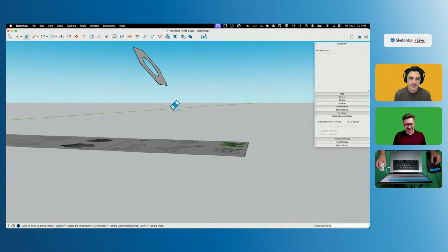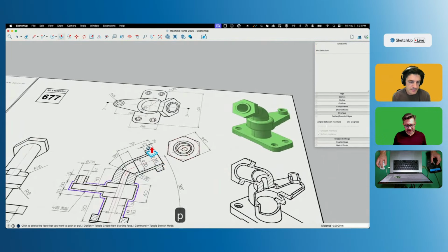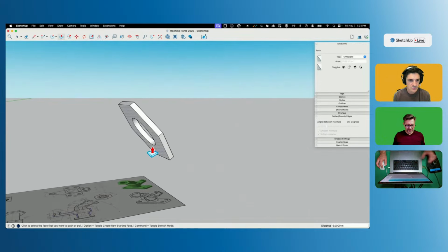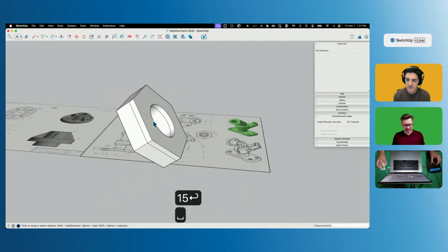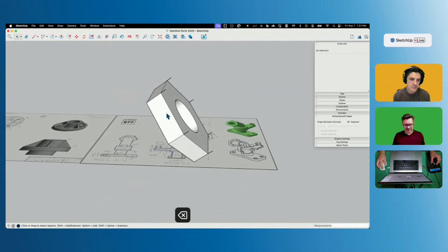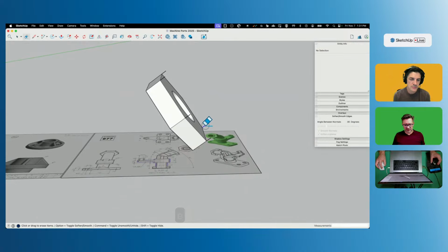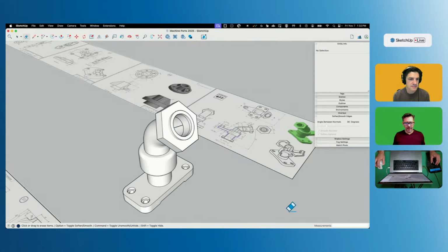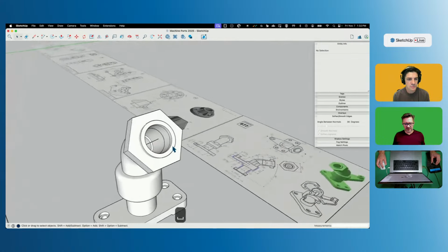And then 15. So actually it does a couple things. It moves back 5 and then it pulls 15. So I'm going to pull this back 5, and then I'm going to say Option and pull back 15. And then double click and delete this piece, and a little bit of cleanup. That should put this hexagonal extrusion right where it should be. So we'll go back to Edit, Unhide All. There we go. Looking good, looking beautiful.